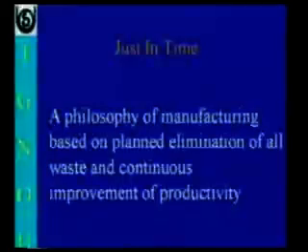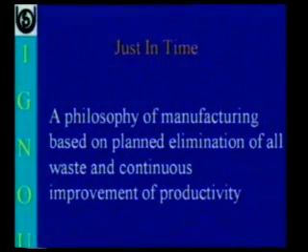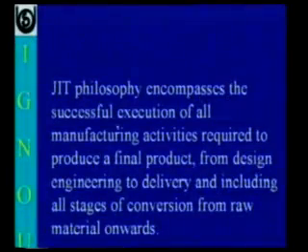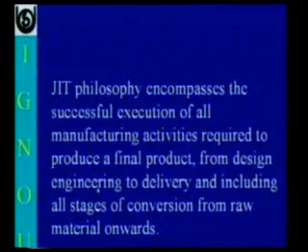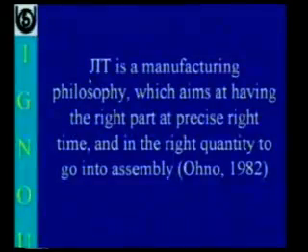A philosophy of manufacturing based on planned elimination of all waste and continuous improvement of productivity. JIT philosophy encompasses the successful execution of all manufacturing activities required to produce a final product, from design engineering to delivery, and including all stages of conversion from raw material onward. Therefore, going by the historical definition, JIT is a manufacturing philosophy which aims at having the right product at the precise right time and in the right quantity go to the assembly.